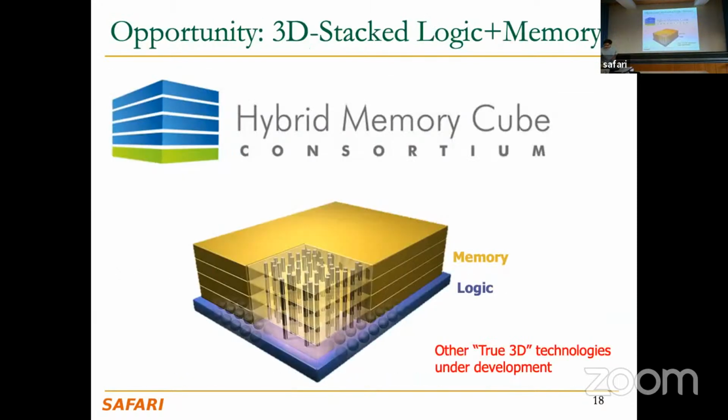One thing as well, before I forget, because it will be important, is that usually these memories are divided into multiple layers, as you see. HMC in particular is divided as well into so-called vaults. Vaults are like the horizontal subdivision of the layers, right? And this area here could be a vault. It has its own memory controller. Here you have another area and direct access through a memory controller residing here. So that's how the HMC memory is divided.